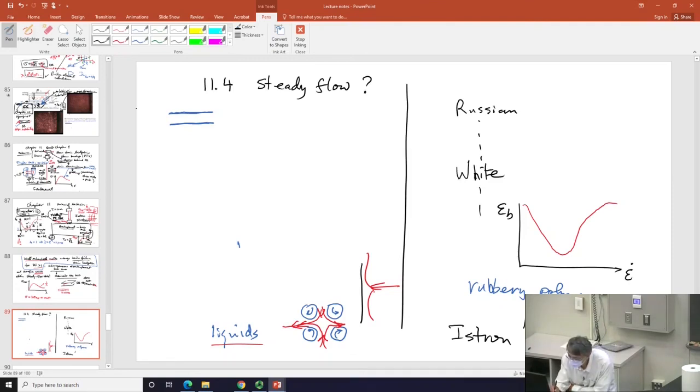Let's have a sample that's liquid-like and put it in between two circular disks. Because of surface tension, it will not flow out. And then it turns out by design, it's always easier to hold one fixed. And then what about just moving this upper one upward? Why not?